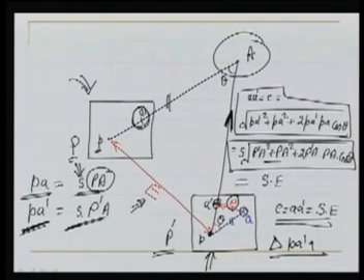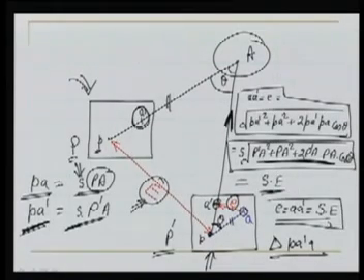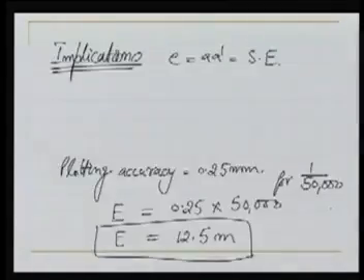Now here in this case, this is nothing but the value of E, because the angle theta here and here is same. So we can write that the error in plotting A dash, how much the point has shifted, is equal to scale multiplied by this shift, or the miscentering error.